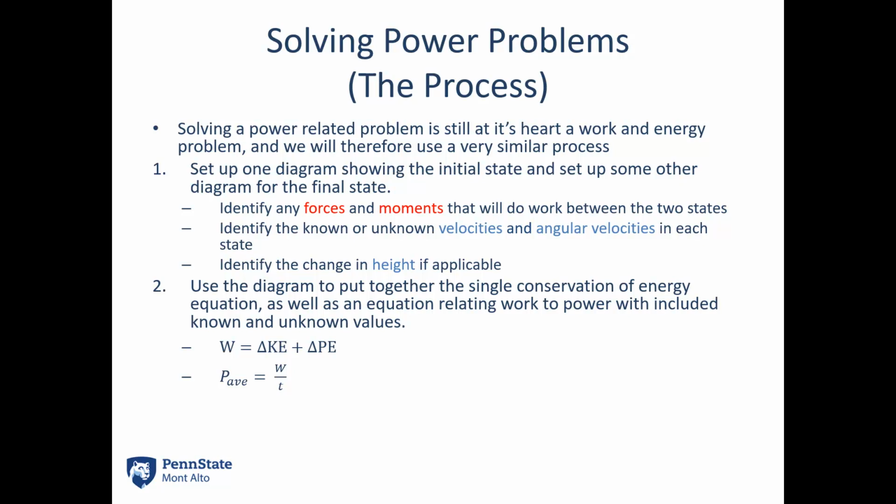So that's our work and energy equation, and just know that we're going to add in our power. We're going to have some sort of power relationship where power is the work divided by time. We might put everything in terms of time, or we might simply need to use that relationship. Each problem is going to be a little bit different, but just know that the time derivative of work is our power. All right, once you have all those equations, put them together. Make sure you've got enough equations to solve for all the unknowns, and solve those equations for the unknown quantities.